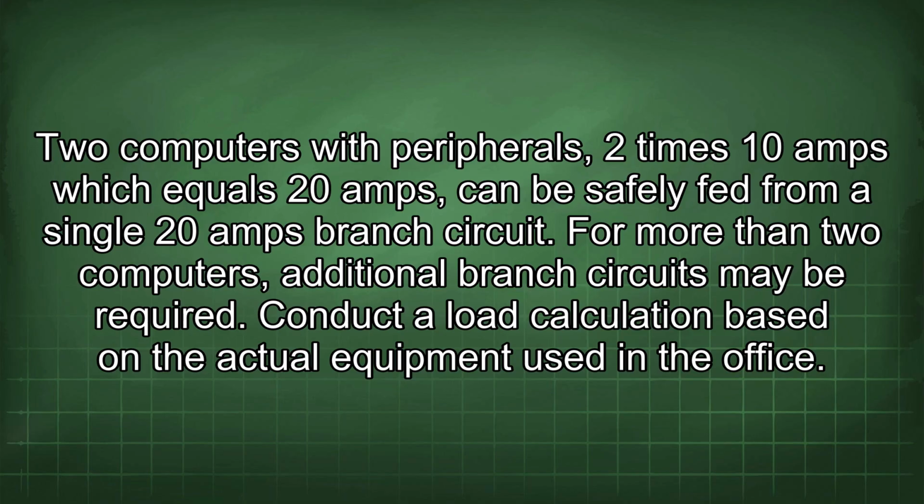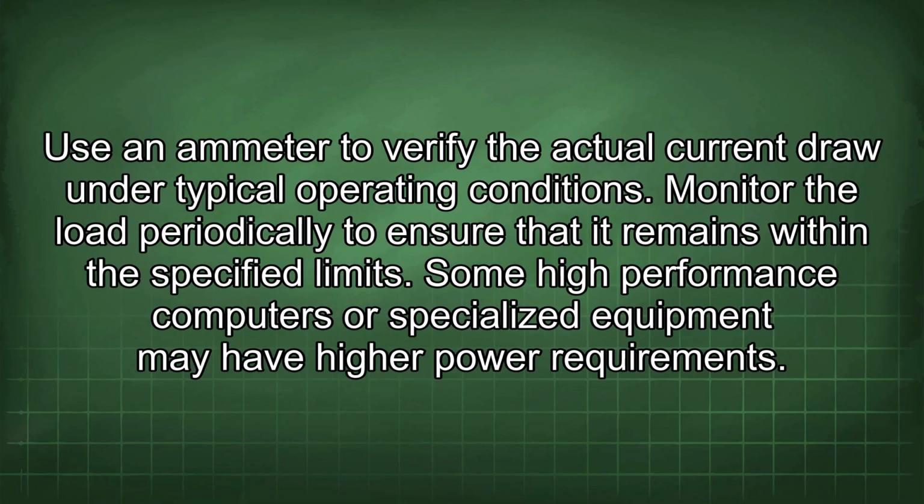Two computers with peripherals, 2 times 10 amps, which equals 20 amps, can be safely fed from a single 20 amps branch circuit. For more than 2 computers, additional branch circuits may be required. Conduct a load calculation based on the actual equipment used in the office. Use an ammeter to verify the actual current draw under typical operating conditions.